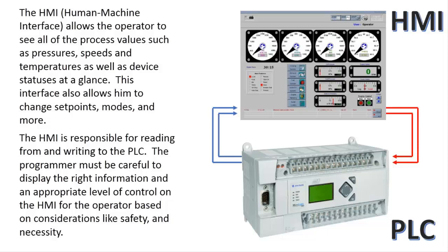But when you're talking about PLCs and you hear somebody talk about the HMI, they're usually talking about one of two things. Either they're talking about a dedicated panel which runs a specific program designed to interact with the PLC, or they're talking about a screen program on a computer which serves the same purpose. And the reason an HMI is important for a PLC program is because, like we discussed in the last section, a lot of times you want to add a level of configurability above and beyond what's programmed from factory.